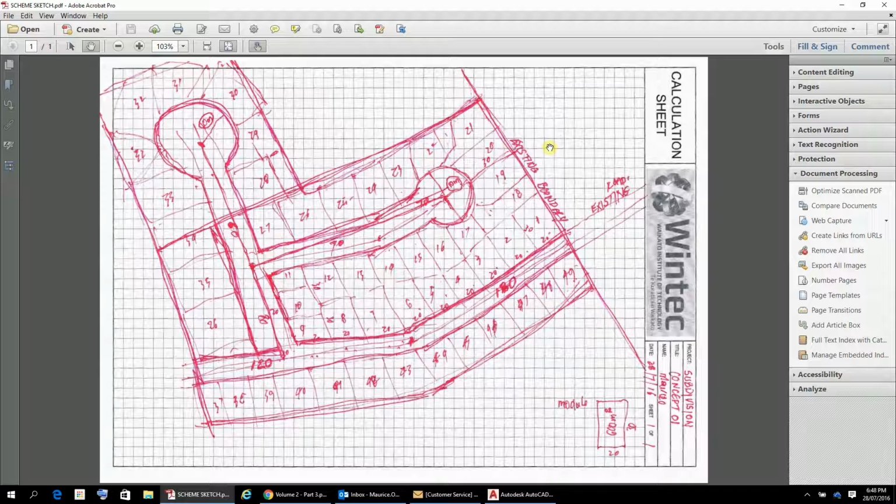Okay, so once I had my road centre lines, I'm going to go with a 20 metre road at this stage, but that's still to be decided. I may cut it down to 18 metres depending on the typical cross section that I adopt. The typical cross section will be the same as the existing road. I'll use one typical cross section through this, as I want to.